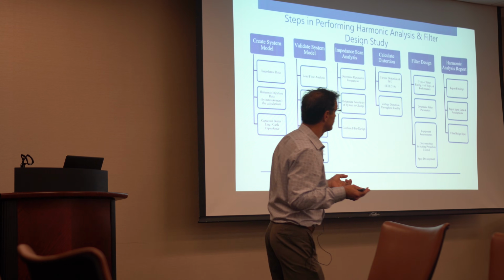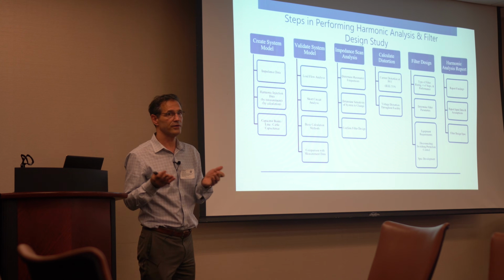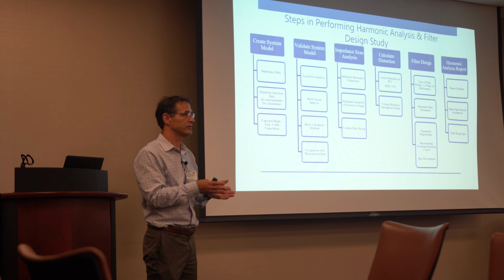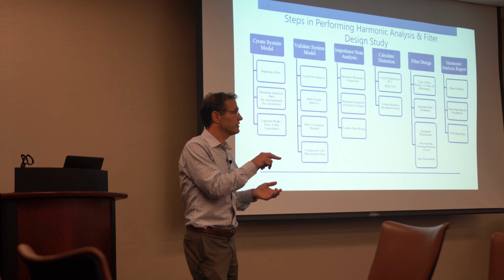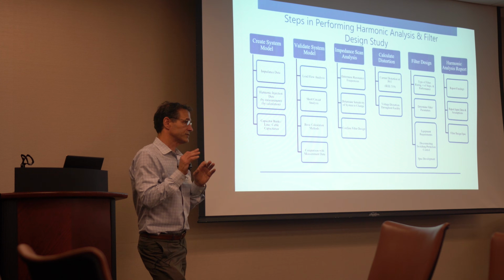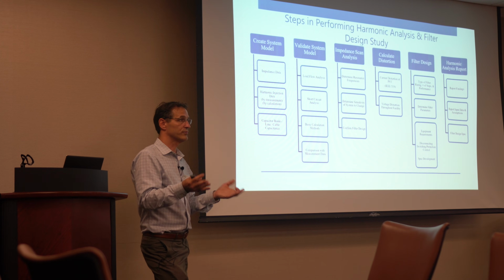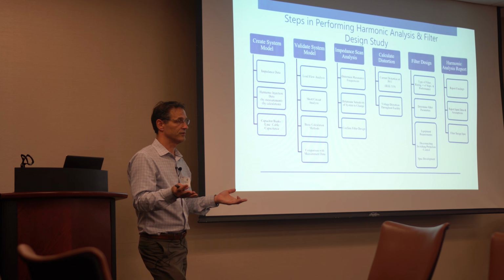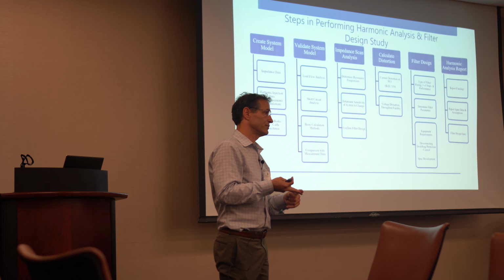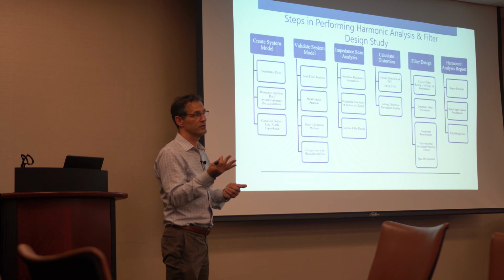Filter design. So say you do your analysis, you got a problem, right? You can do a filter design. The filter design process is, for us, to actually use a spreadsheet tool. We have a spreadsheet tool on our website for designing notch filters, C-high pass filters, and high pass filters. Those are the three types of filters that are used.